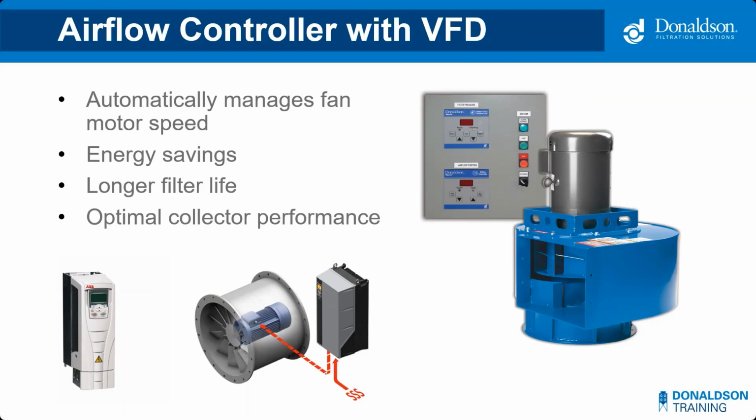We used to specify VFDs really only for larger systems when this type of technology was new to the market. But as design has evolved and costs have come down, we're now seeing them specified on even small systems. If the budget allows, the VFD, or variable speed control electronically, is the way to go, hands down.